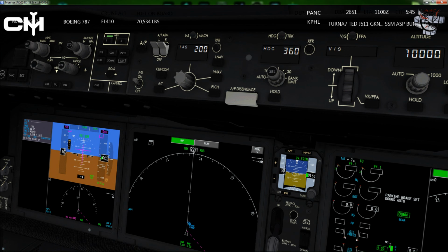And let's see what else we got here. Weather switch is off. That's good. Traffic and terrain switches as needed. We don't need those right now. Auto throttles are armed. See, I just got a little ahead because I knew that was going to happen. Autopilot disengage bar, that's this one here, has already been taken care of. Heading track reference switch as needed. That's these ones up here. I don't change heading and track. I don't change vertical speed to flight path angle either.